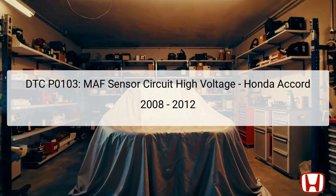When the signal from the MAF sensor exceeds expected values, it triggers DTC P0103, indicating a malfunction. Understanding this error is important as it can lead to reduced engine efficiency and increased emissions. The MAF sensor is typically located in the intake air duct between the air filter and the throttle body. Analyzing freeze data and onboard snapshots prior to troubleshooting is vital to diagnose the issue accurately.